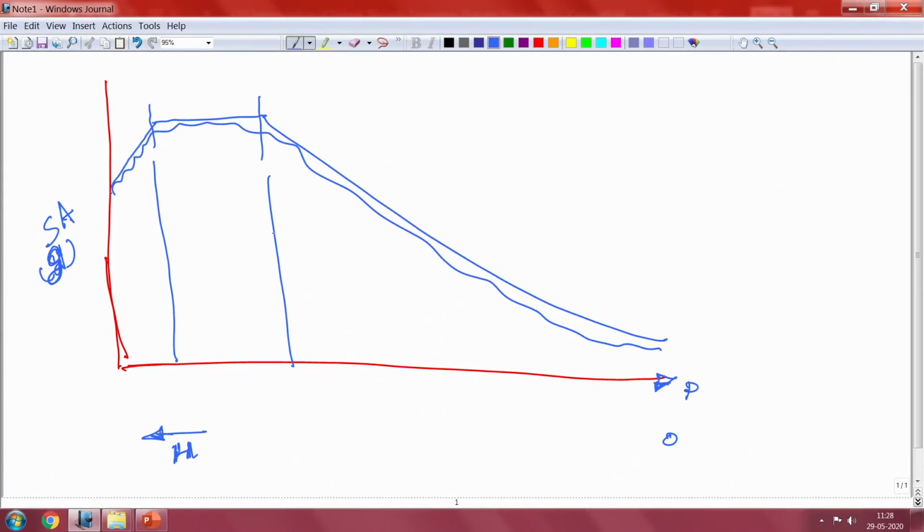So this we have discussed, that it is the spectral acceleration or PGA. When the structural period is 0, your input motion will have the same signal, and that maximum input motion is the PGA. Okay. So this is basically a response spectrum. This can also be plotted in the tripartite plot. So this is for one ground motion.